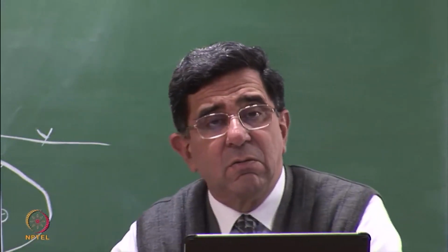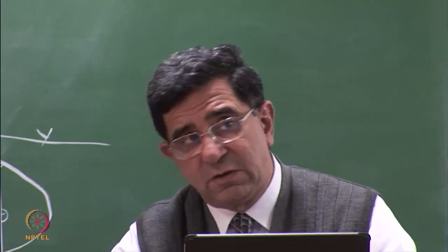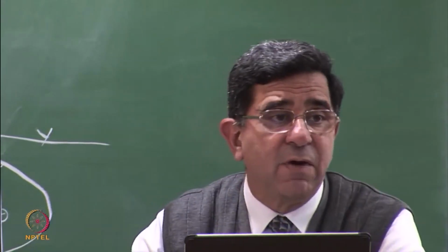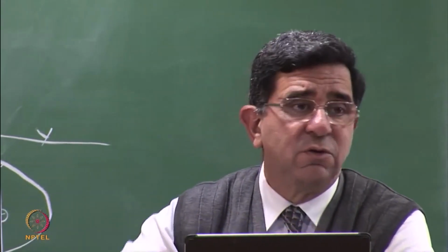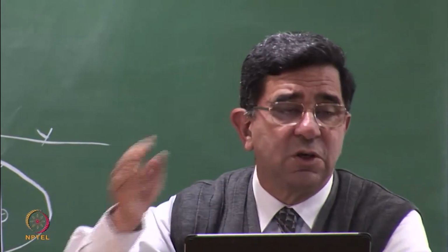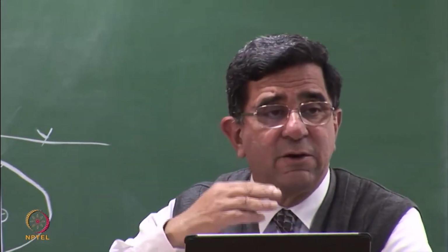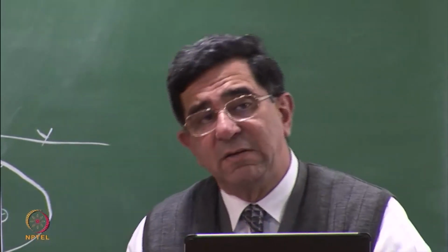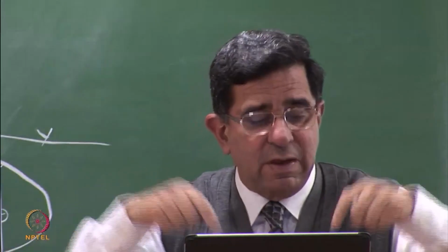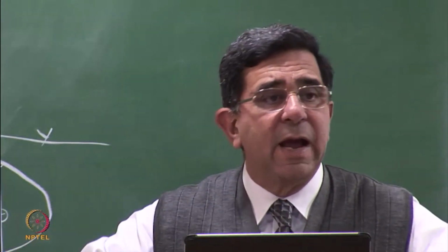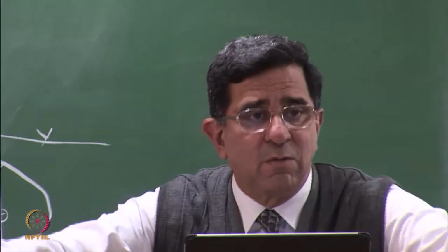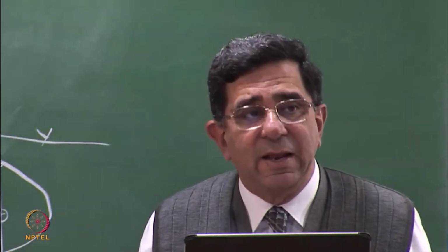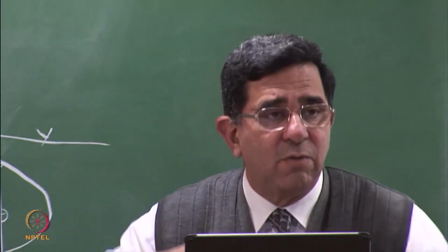Now, the advantage of geophysical or indirect equipment is that it can be done very fast. So, you may do some geophysical investigations. For example, you would just do an electrical resistivity or an electromagnetic inductance survey right on the ground surface. You will have devices which can be rolled on the ground surface. You can have devices where electrodes can be put, but a reading can be taken in 10 minutes and then they can be moved forward. Or you also have electromagnetic devices which you can carry in your hand. You have a meter in front and you can move up and down.